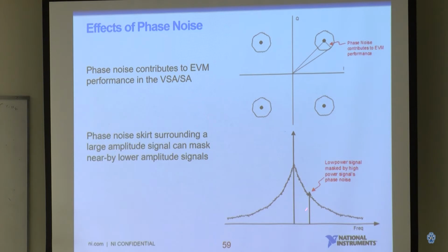And this is also about why phase noise matters in spectrum measurement, because remember you have a big Christmas tree, and you try to measure the signal just next to the main signal. Because your phase noise is too high, it will cover the low power signal you try to measure next to your CW, right? So if your signal is under the phase noise, that means you're not able to measure any signal next to the CW signal.